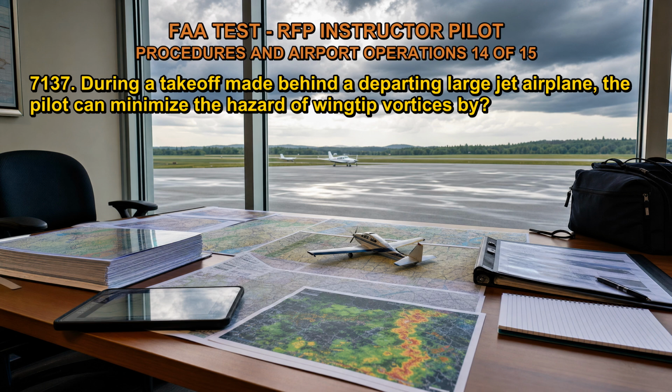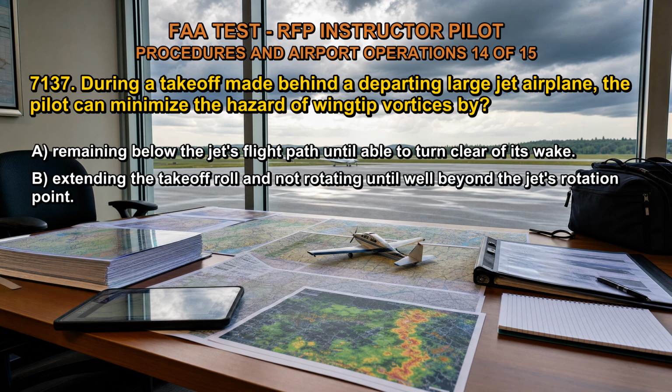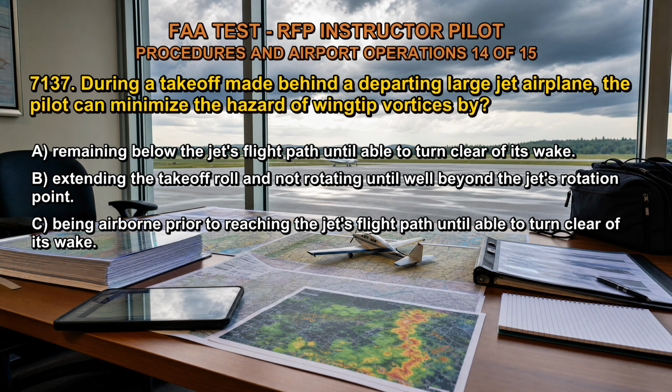7137. During a takeoff made behind a departing large jet airplane, the pilot can minimize the hazard of wingtip vortices by A. Remaining below the jet's flight path until able to turn clear of its wake. B. Extending the takeoff roll and not rotating until well beyond the jet's rotation point. C. Being airborne prior to reaching the jet's flight path until able to turn clear of its wake.